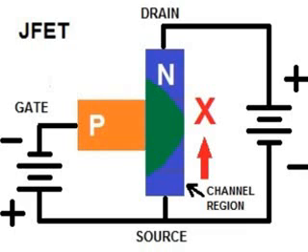So this is how the FET works. The reverse bias voltage at the gate causes channel resistance between source and drain to increase, and it goes to infinite resistance at the pinch-off voltage. Making the gate voltage more negative than the pinch-off voltage won't cause any further change in the channel resistance, since it's already as high as it can get, infinity. It's in cutoff.